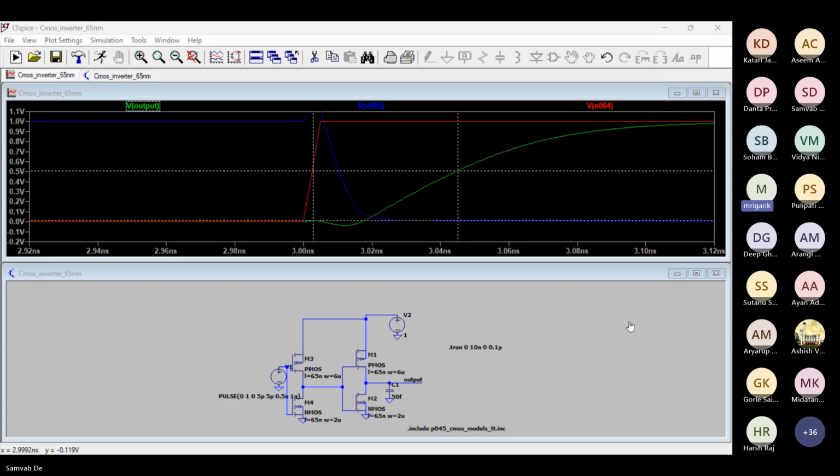of the first inverter. So when you are increasing the size of all these transistors, you are not only reducing the on resistance, you are also increasing the capacitor value at the output of the first stage and also the output of the second stage. Because at the second stage output, although we have a big capacitor of 50 femtofarad, if you keep on increasing the MOSFET sizes, it will eventually start increasing the capacitor also. So the net capacitor at the output of the first inverter as well as the second inverter will go on increasing if you go on increasing the W by W, and right now we are keeping the L minimum.